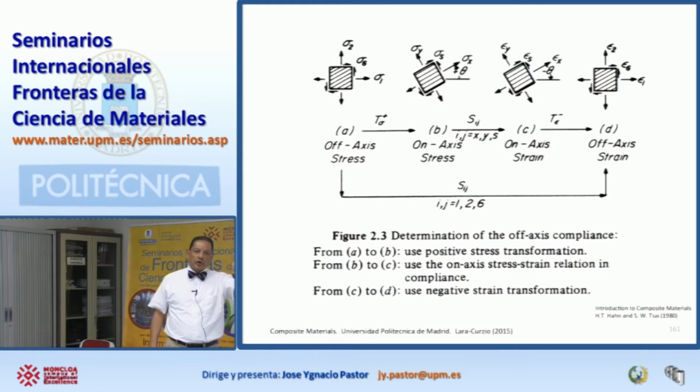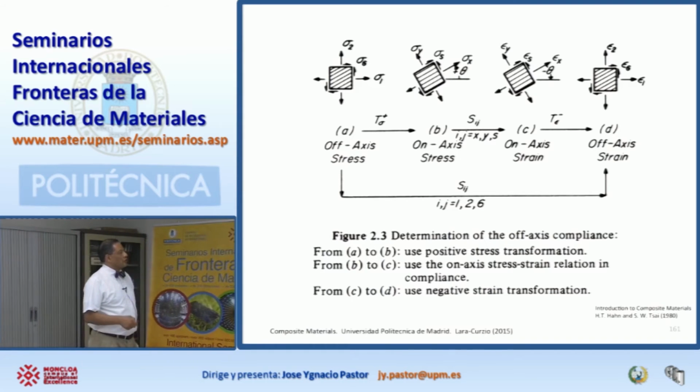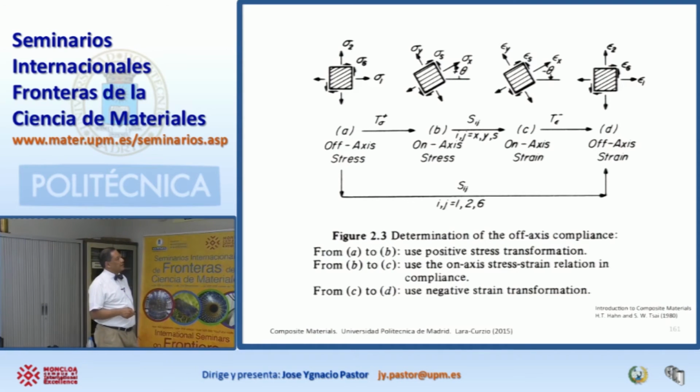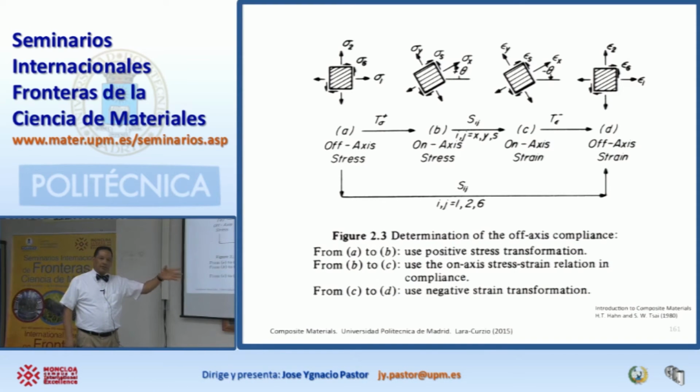You're going to have your directional cosines, and then you can rotate, and that will give you the result. So this is how we calculate the strains from stresses whenever you have some arbitrary angle applied to the composite. So you're an engineer at Boeing, you have your fuselage, and you're playing with this. You have a computer, and the computer is going to be doing all of this for you. And all you have to do is play what-if scenarios.